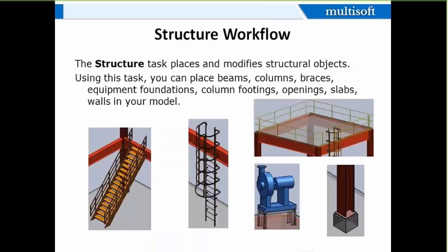In the same way, you can place some ladders, staircase, and handrails, as I told, footings, and the equipment foundations also. It's a single click, just a click of a button, you can place the foundation. That's why I told earlier, it's a rule-based software. As per your client requirement or the project requirement, your catalog admin or a symbol admin or programmers who are there, they will model, they will create all your backend symbols. You have to just click it, automatically it will be placed.